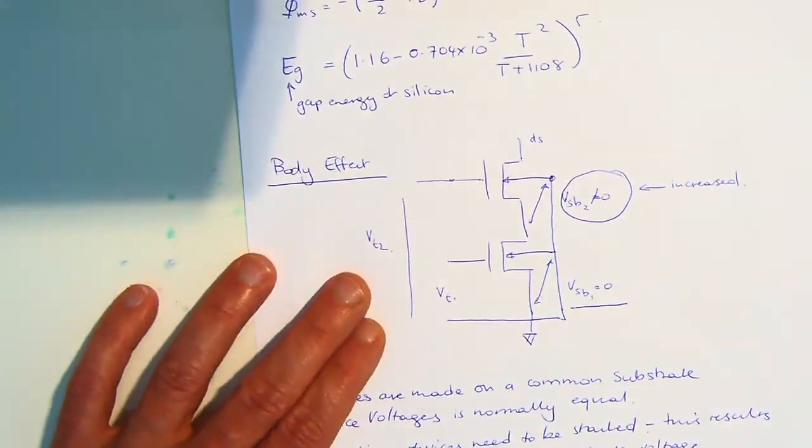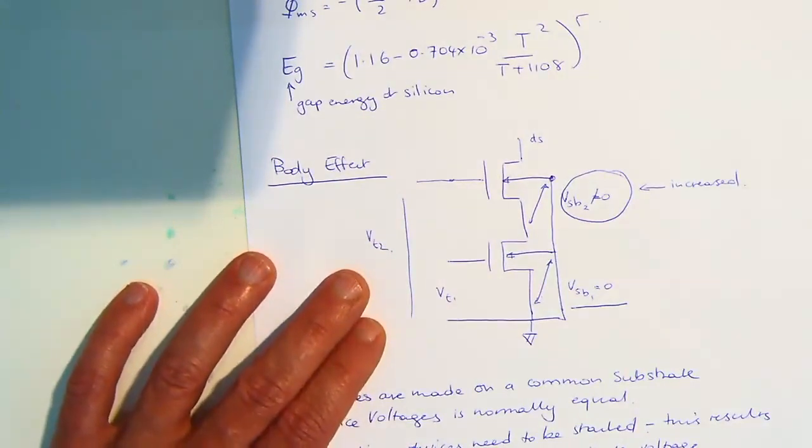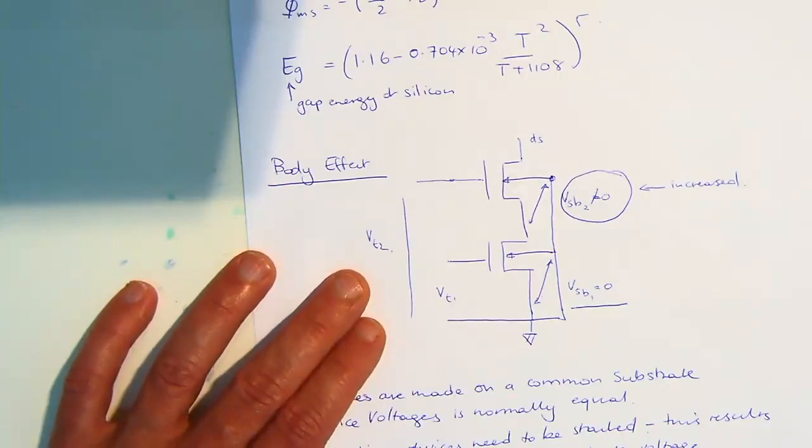And essentially, when you're trying to get more power out of a power amplifier, the power that you get out of it goes as V squared on R, right? R is the output impedance, and V squared is the voltage that you can actually swing.